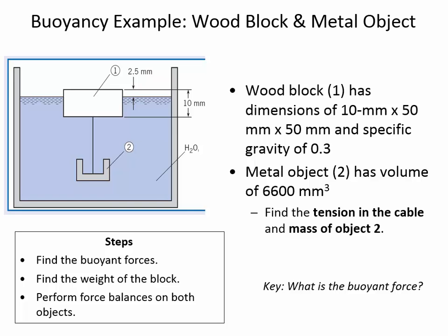So here's the tricky thing: we're talking about the unit weight of a solid, not the unit weight of the liquid. There's two different unit weights. In order to find the weight of that concrete block, you have to ask yourself what's the unit weight of the concrete? I think they give you that. So since they give you the unit weight of water and of concrete, and you will have previously calculated the required tension in that line, the only unknown is the volume of concrete that's required.